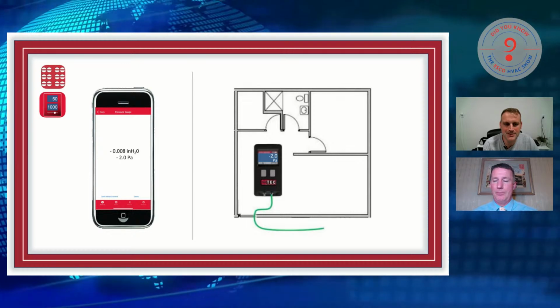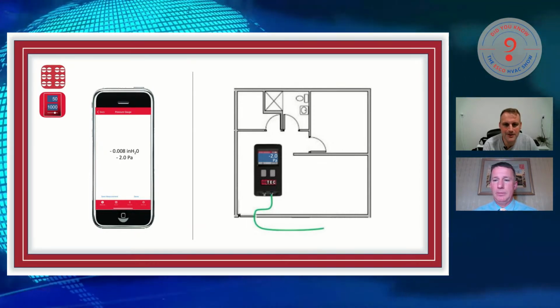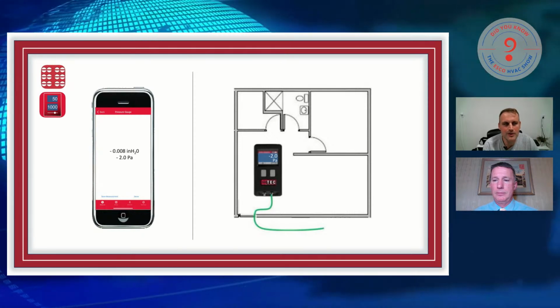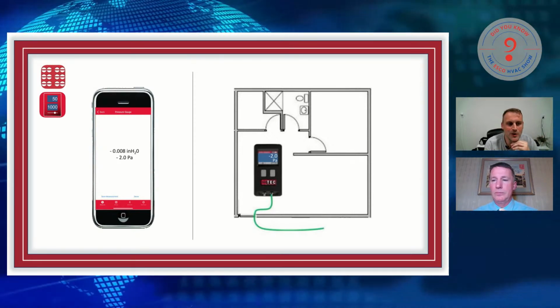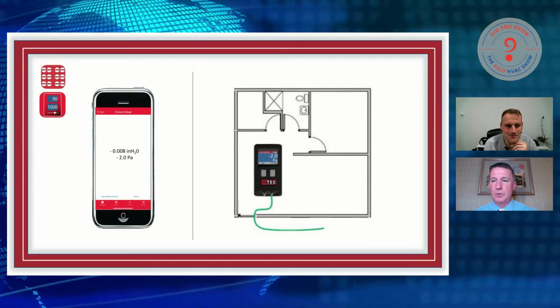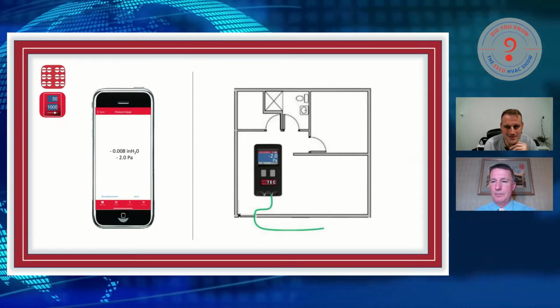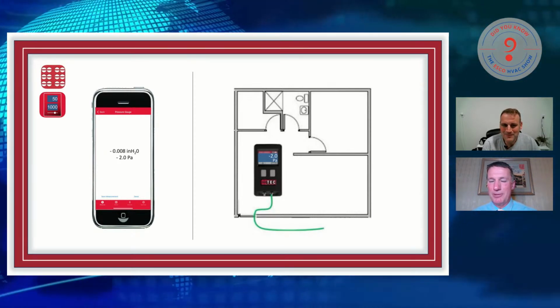But when you fully understand how to do a dominant duct leakage test and you're confident with it, you will know that before you pull out, say, a duct blaster and go measure leakage, it's worth it, because you've already identified significant leakage with a test that took about a minute. So you know you're going to find something. It's the blood pressure test before the stress test.